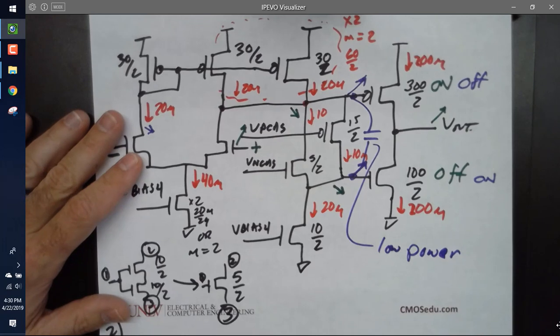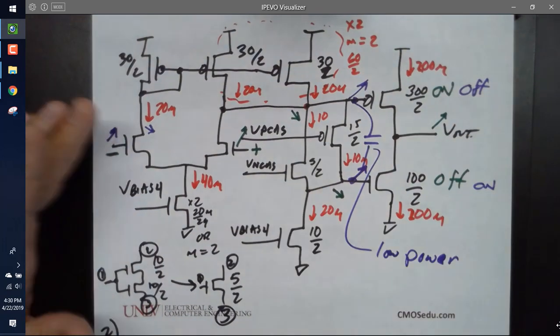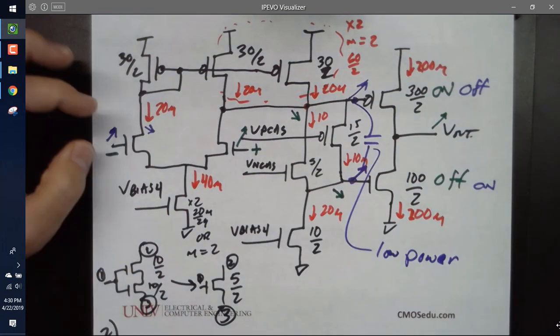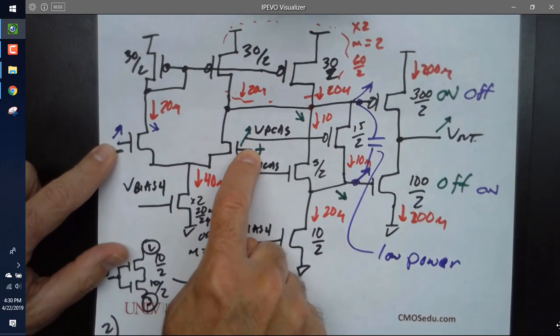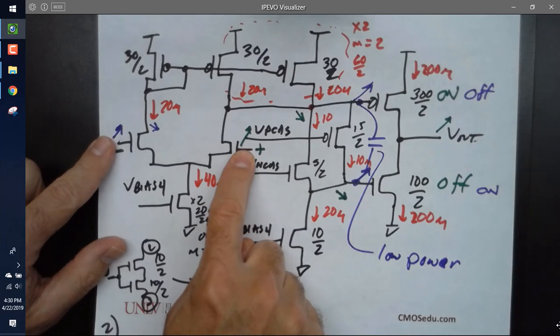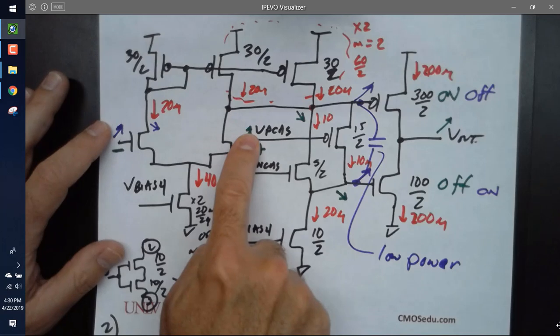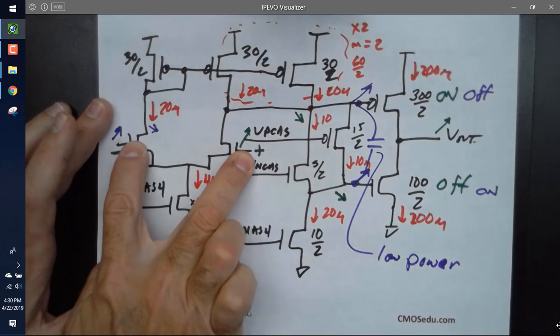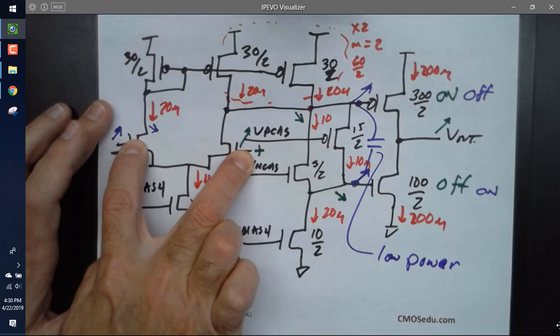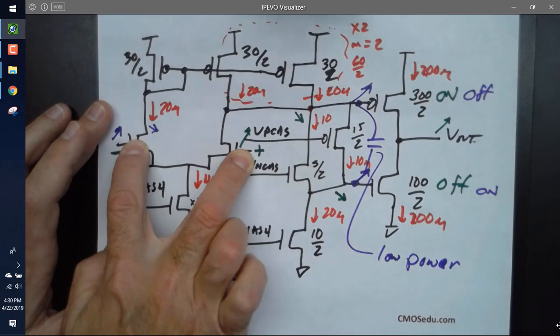All right, any questions before I go through each of these circuits? Now, notice down the road, not today, we could put a PMOS diff amp here and put them in parallel, have them both on, one off, one on, the other off, the other on, so that we have input common mode range that extends basically rail to rail.